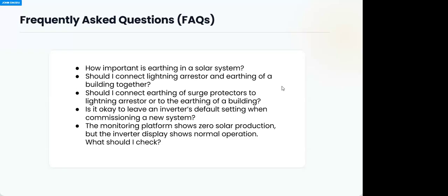Of course, all this has been programmed. So the battery will not demand a current rating higher than its own rating. If it is 200 amps, it can demand that 200 amps for charging. So that is why it is important when you are choosing your cable size and everything, you should know that this battery, because it's communicating, can demand anything. So you should be ready.